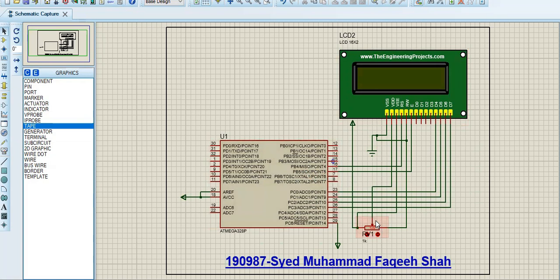It is attached to VDD, and this output is attached, ground is attached to RW, and input is being given and attached to VEE. We are using 4-bit inputs, that is, we are using the D4 to D7 inputs. So if I run a simulation,